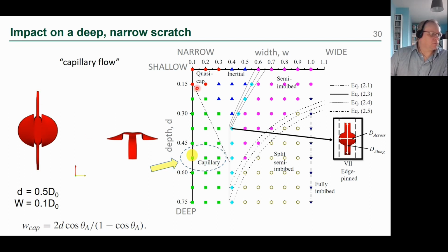That's because of the capillary effect, it travels along the channel, and so that can lead to some elongated parts of the liquid. So this might be a problem for printing if you were printing two separate lines of a circuit parallel to each other. You could actually create a short circuit between them with this kind of connection.